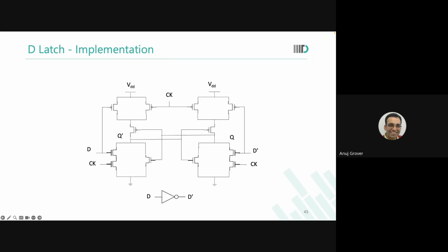I cannot turn it off. Are you with me? That parallel structure on the top was used for the write operation, so that when I want to write into this latch, one side is driving 0, the other side is not fighting that 0. Are you with me? But now the other side is going to fight that 0.